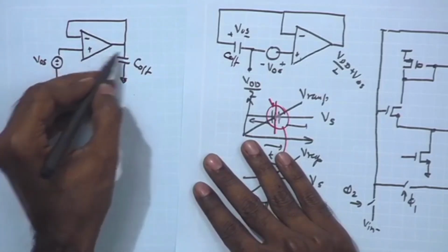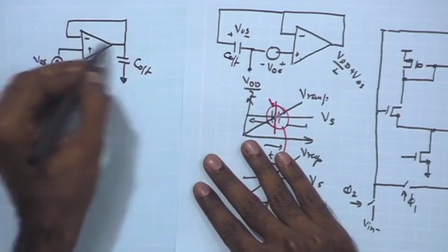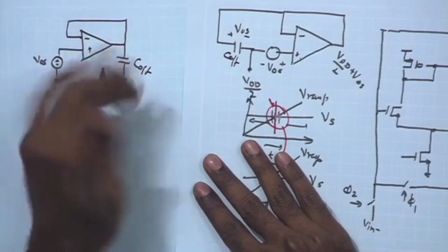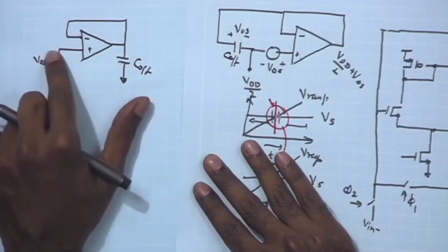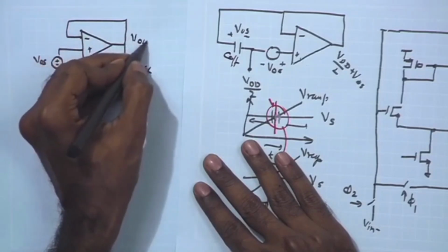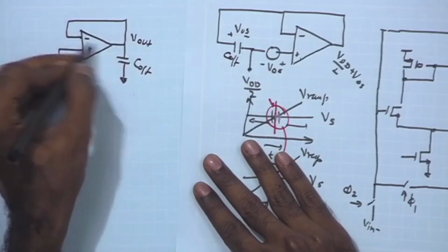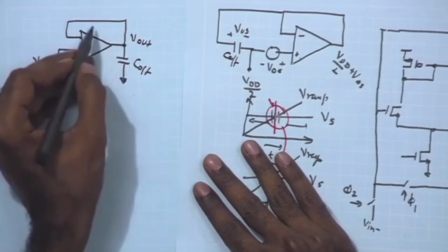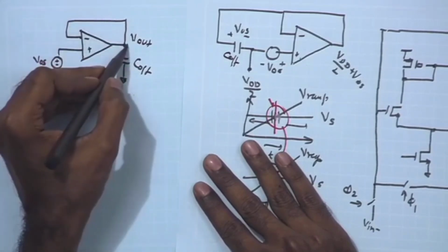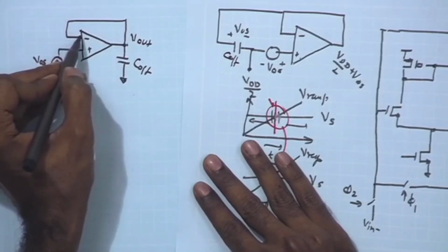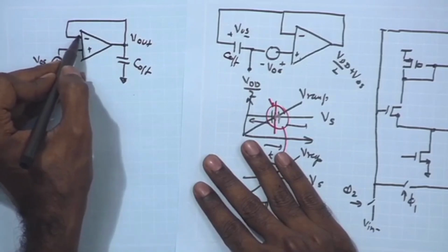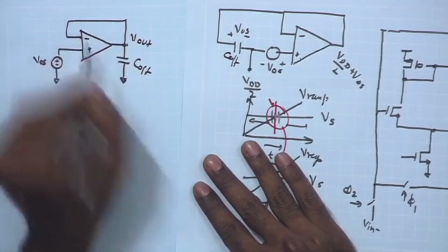Now, in this case, once again we have the output voltage being fed back to the input terminal in series. Therefore, at the input we have series configuration, output voltage V out is being sampled and fed back to the input. So, of course, at the output we have shunt, and the feedback factor is unity, because we are just sampling the V out, and the feedback signal to the negative terminal of the op amp is just the V out as it is.